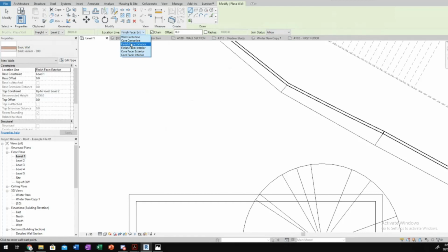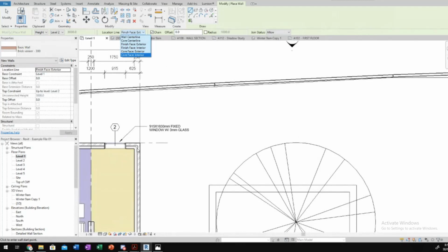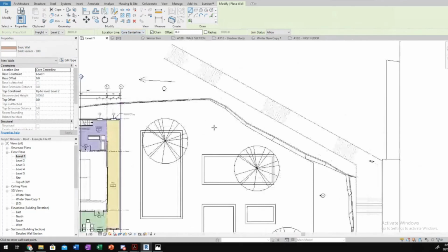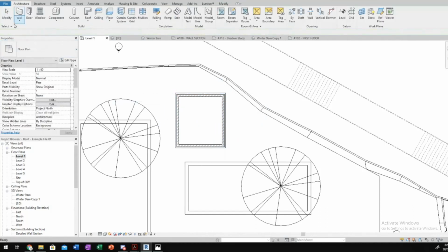You can also change it so that you've got it in your core or your center line, because if you have grids, right, maybe you want to base them off the centers of your walls, not the outside of your walls. So let's go by the core maybe. And as you can see, Revit loves to align everything. So as I go up, it'll have dots and it'll want me to align everything, and there you go, we've got a chain of walls.